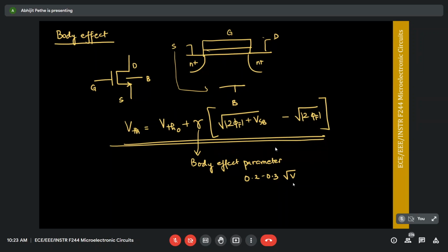Now, the impact of gamma is important in planar transistors. When you start working in FinFET, nanowire and nanosheet designs, body effect doesn't exist in fully depleted devices. So this is something vestigial of the long channel planar transistors that we've had, and for completeness, I've put it here. But in FinFET designs, we won't really use this. In the real world, you're not going to be using this most of the time.